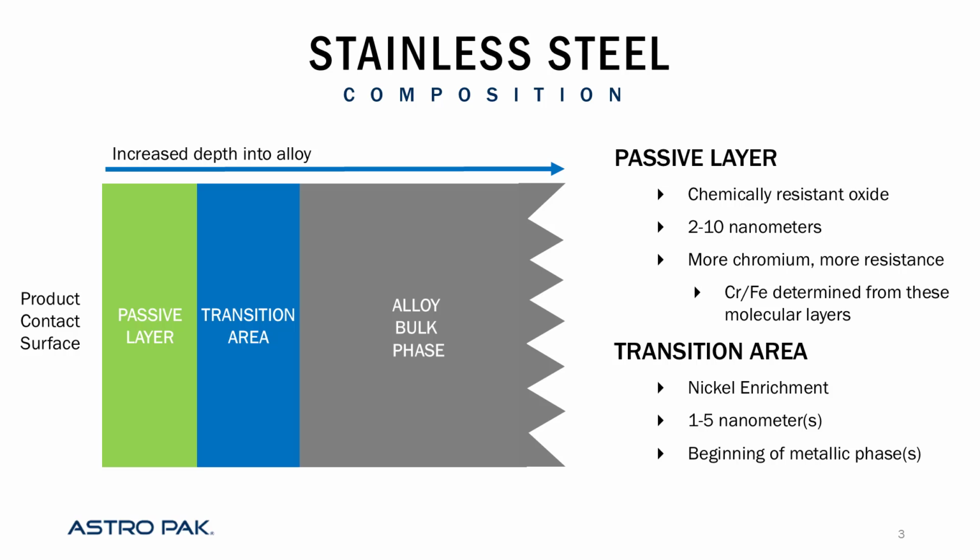A leading metric to determine how resistant this passive layer is something called the chromium to iron ratio. So you take your stainless coupon, you put it under an advanced microscope, and it's analyzing the first few molecules of your coupon. The amount of chromium relative to the amount of iron in that oxide layer in the 2 to 10 nanometers is the chromium to iron ratio.